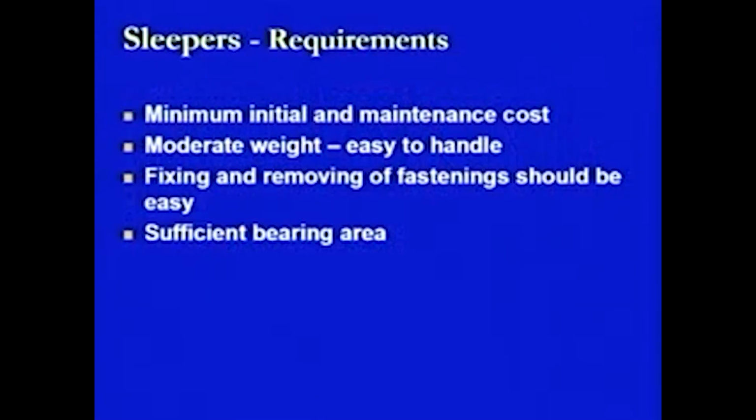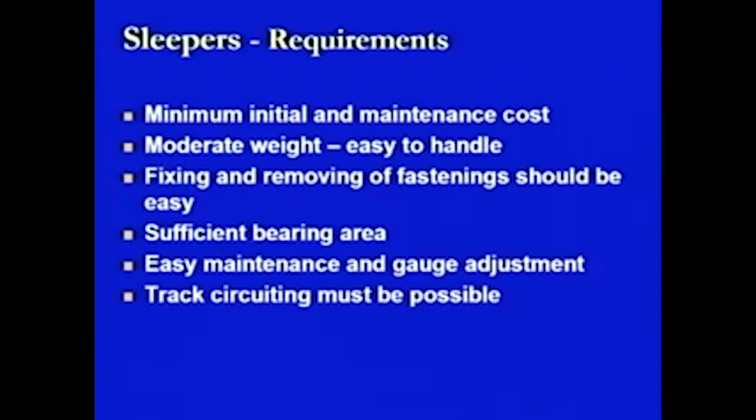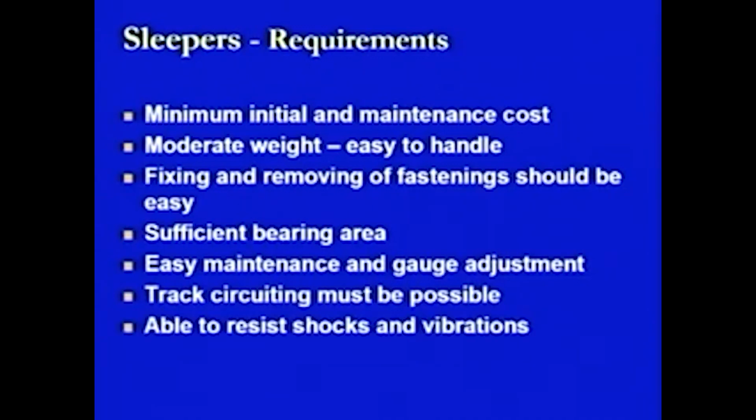Sufficient bearing area should be there for all the sleepers, so that they can transfer the load to a wider area of the ballast cushion. The maintenance should be easy and the gauge adjustment should be possible using the sleepers. Further, the track circuiting should also be possible. Now, slowly and slowly we are moving towards the electrified track conditions. Therefore, this is another important consideration and requirement of the sleepers.